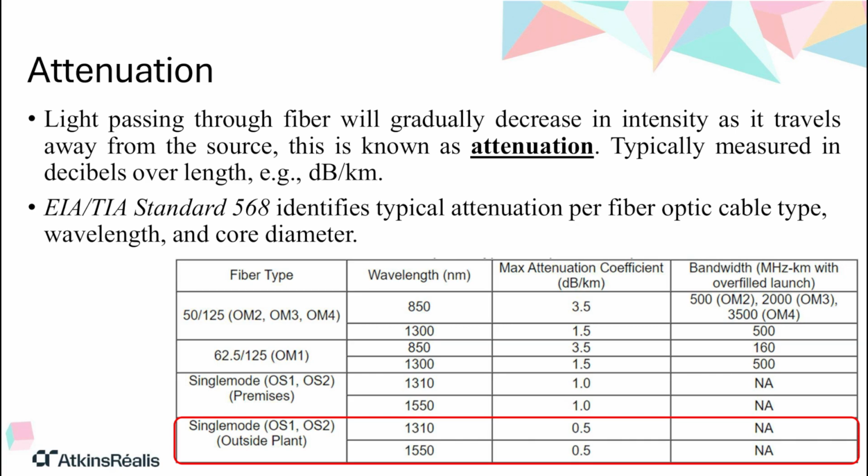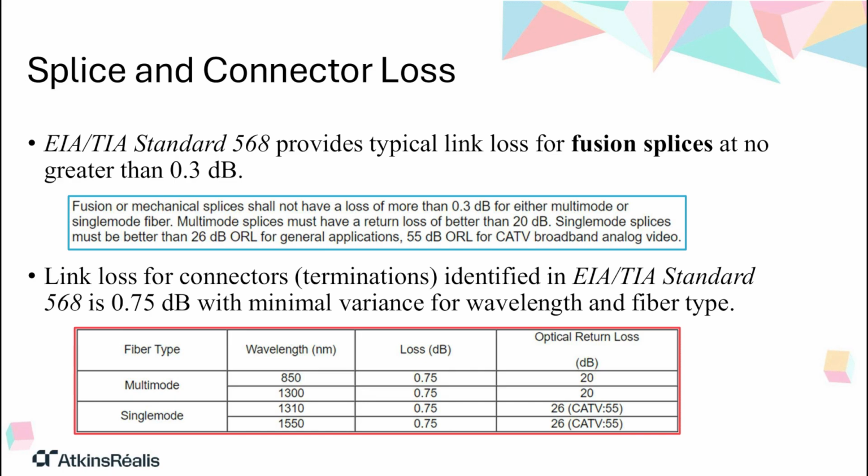And the other connection type? Terminations. Yep, connector loss. Where the fiber plugs into a patch panel or equipment, we might say 0.75 dB is acceptable. FDOT, they'll want something like 0.3 dB for factory polished connectors and maybe 0.5 dB max if it's terminated by hand in the field. So across the board, attenuation, splices, connectors, the FDOT standards are significantly tougher than the general industry ones.